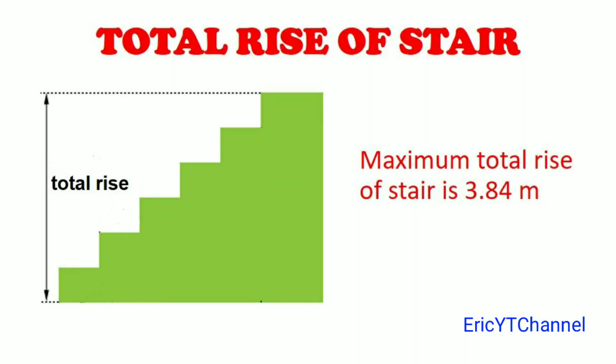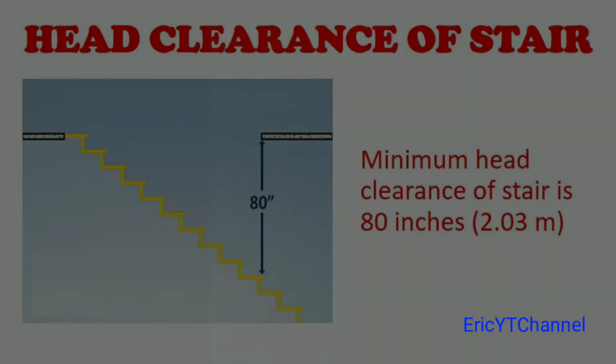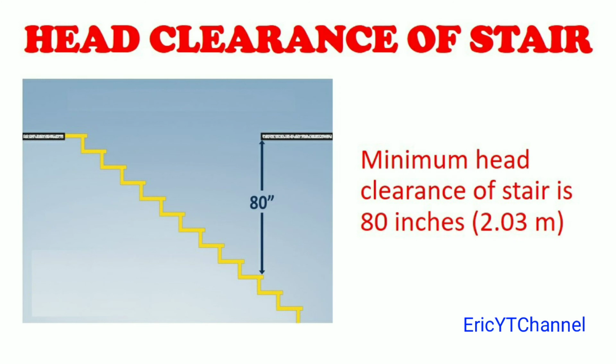Total rise of stair. Specification is maximum total rise of stair is 3.84 meter. Head clearance of stair. Specification is minimum head clearance of stair is 80 inches or 2.03 meter.